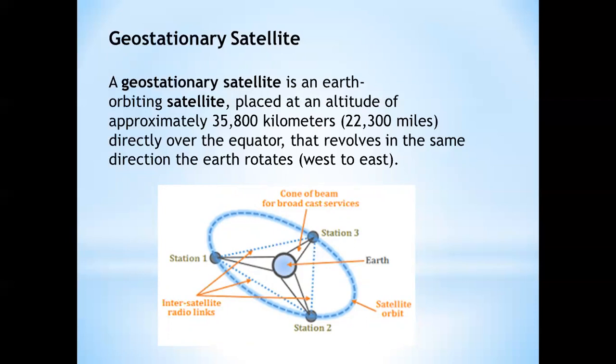The advantages of geostationary satellites are that they are much above the inner radiation belt, which poses a problem to the solar cells of low altitude satellites. The solar cell can get solar radiation for almost 99% of the orbital period. Therefore, energy storage is not necessary. The Earth's magnetic field is weak at such a height. Therefore, the adverse effects of magnetic fields are absent. Large coverage area: a geostationary satellite is visible from about 42% of the Earth's surface area. Therefore, three communication satellites can cover the entire surface area of the Earth as shown in the figure.